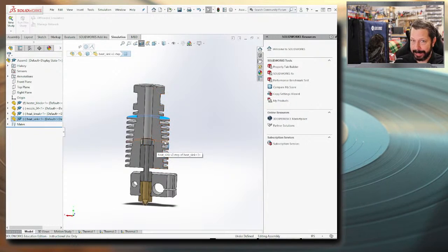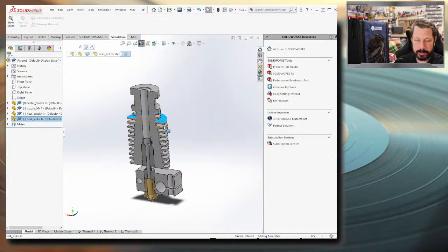The reasons it might not be are, number one, the fan blowing across these fins has quit working. Maybe you took it all apart and put it back together, but you put the fan backwards. Typically this fan has a little sticker label on it, and it needs it pointing towards the heat sink. That's usually indicating the area that the air is going to be pushed.